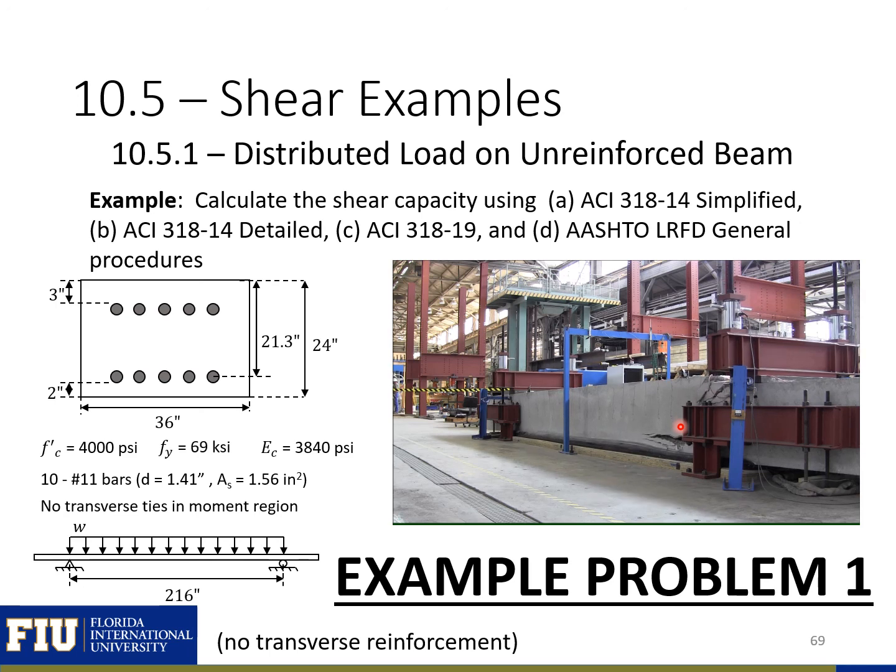As soon as the crack develops, the beam fails, and you can see the cracking develop at the location of our longitudinal reinforcement, which helps hold the crack together until we have another crack develop and full failure of the beam.